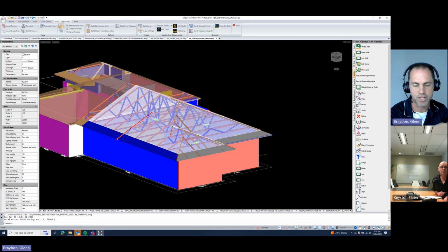So it's obviously a mistake by the detailer, but it's not going to get picked up because you can roll the webs in 0.55, obviously, if you wanted to. And the truss still passed, engineering still passed with 0.55 webs. Maybe you've got to put some extra screws in the connection, but that's probably not a big deal. They've made a mistake with maybe 1 truss, 10 trusses. We want to just, instead of going back and redetailing it, roll it in 0.75. Can we do that? How do we do that? What's the best way to go forward there?